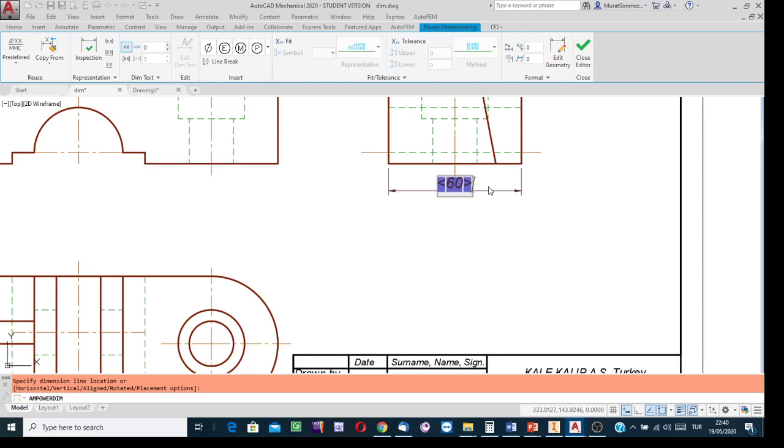And then in AutoCAD, after making such a click, the measured distance, of course, in the background is multiplied by the inverse of the scale factor, and the indicated number is not the dimension of the projection, it is the dimension of the feature, the dimension of the object. It is under, say, construction edit mode. Well, have a look, the dimension is correct. It is in the correct order. No mistake in the drawing. Then this means it is okay. Press enter.